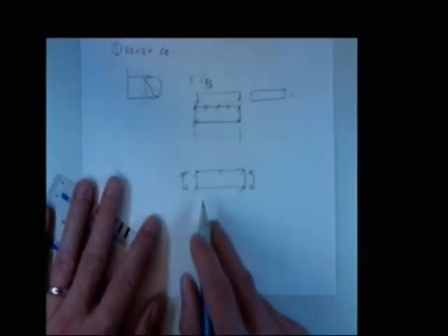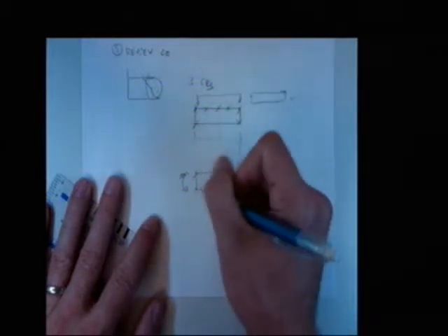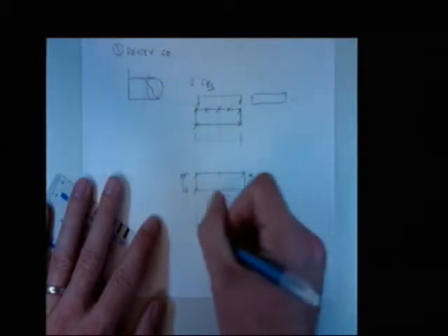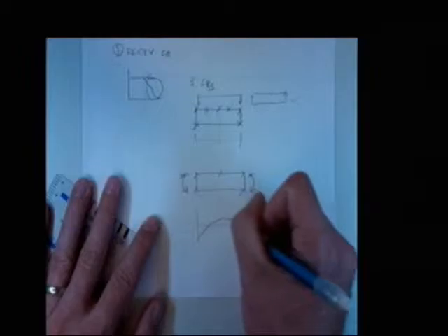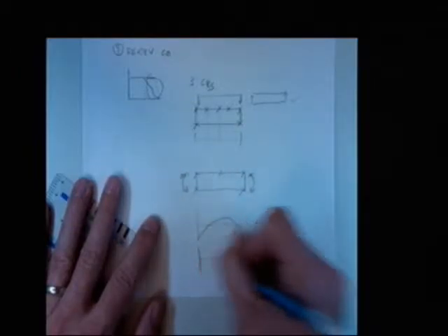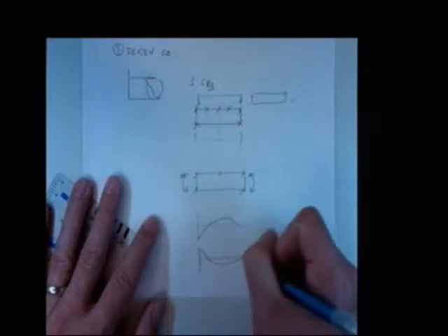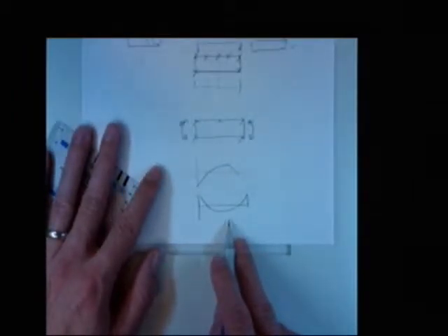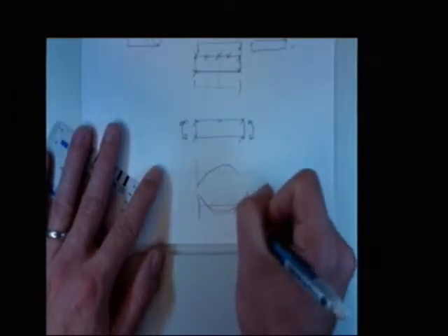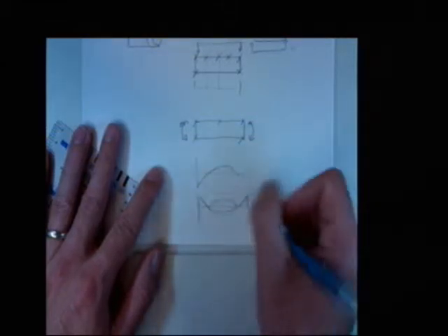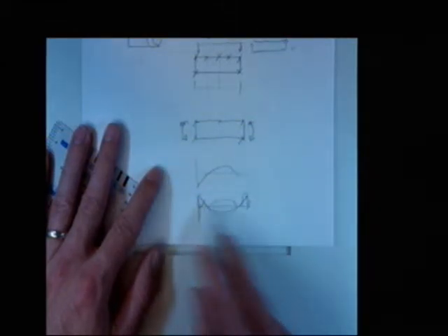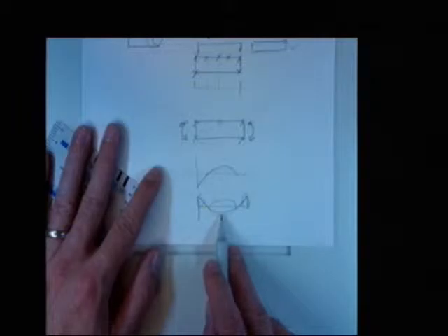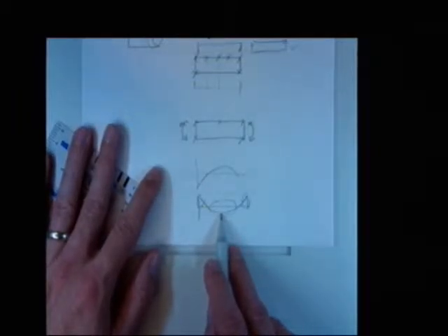So this circumstance where our moment diagram may not be constant, our moment diagram may look something, well, I drew it wrong. Moment diagram may look something like this, right, because we're talking about uplift. This idea where all of this bottom flange is in compression and these are not. These are actually helping it, and these are actually in compression. And structural engineers, for whatever reason, are not very good at doing 5 pages of differential equations to solve the answer to this.